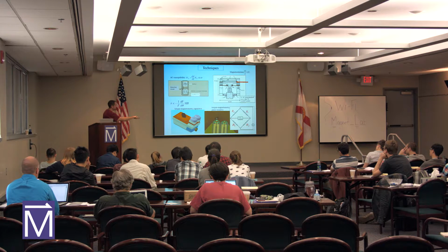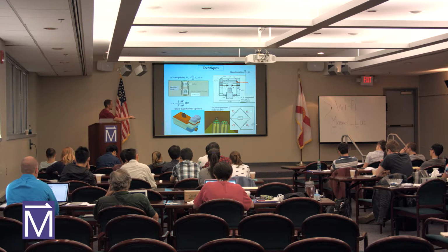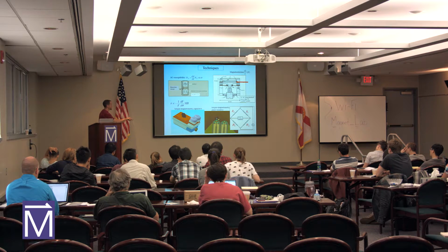So we just take these two resistors here and we incorporate them as part of a Wheatstone bridge circuit. The two more resistors are at room temperature. We have a couple of potentiometers outside in our breakout box, for example. And when these four resistors are put into this configuration, we cool down our sample to low temperatures. We start at zero field, and we balance the circuit out so it's at zero for our lock-in measurement. And when we sweep the magnetic field, as this sample tries to move up and down as its magnetization changes and creates torque, then we'll see the voltage signal oscillate about zero.